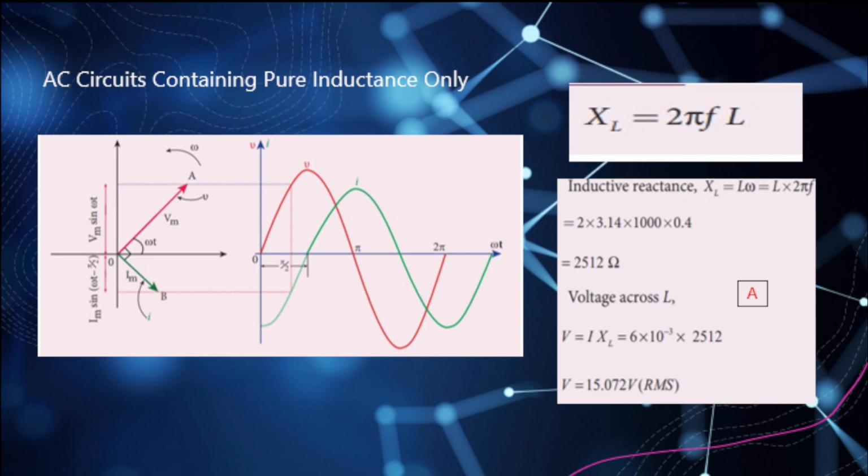For a steady state current where frequency equals 0, our inductive reactance, or XL, will equal 0. Thus, an ideal inductor offers no resistance, as I previously stated, and as we learned when we studied steady DC current in our DC circuit series. However, this will not be the case when we are dealing with an alternating current. Recall, inductors pass DC, but block AC. You probably recall me mentioning that in the past, and if I didn't, I'm mentioning it now.